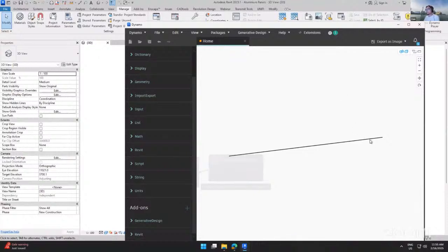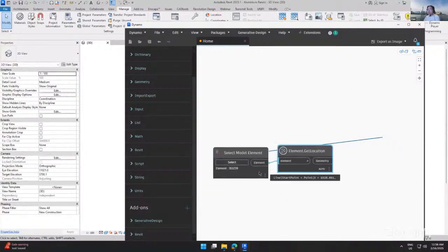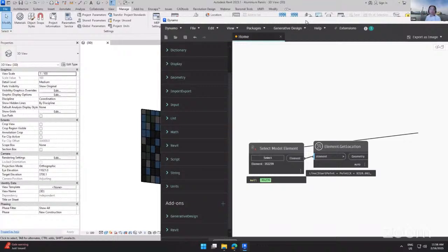And remember, I talked about the intersections. So you can now examine, from this wall, that you have intersections. Then you need to determine that you keep here to here, and for the other wall, you keep here to here. Then you can trim it, and assign this line back to the wall. That is the concept of doing that. The detailed execution I cannot explain here, but this is the workflow that you can explore.